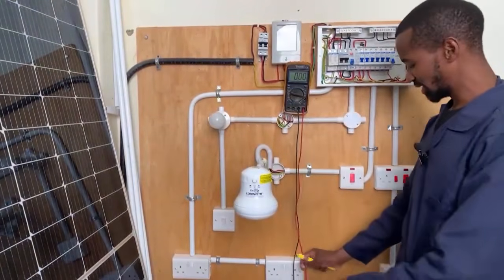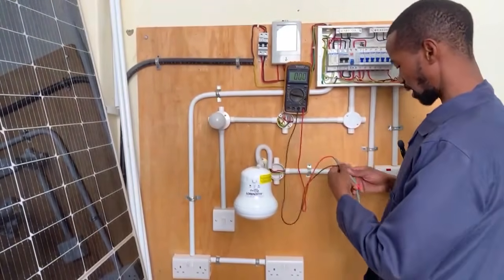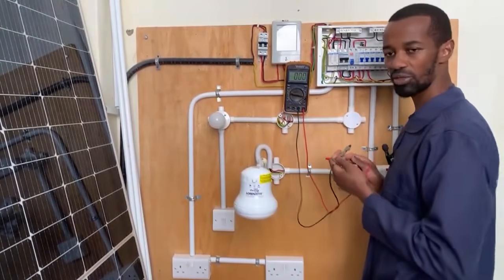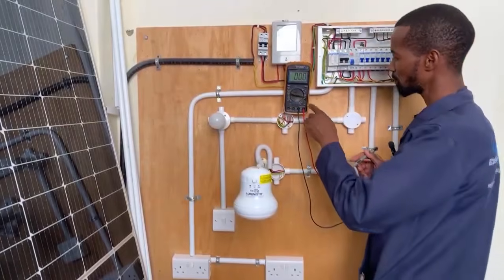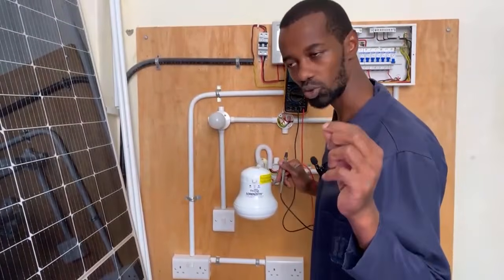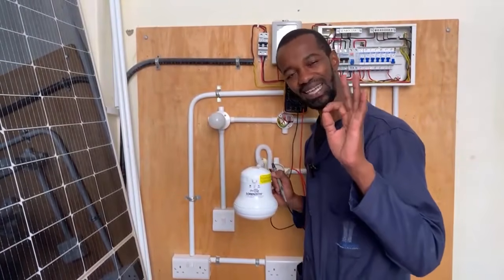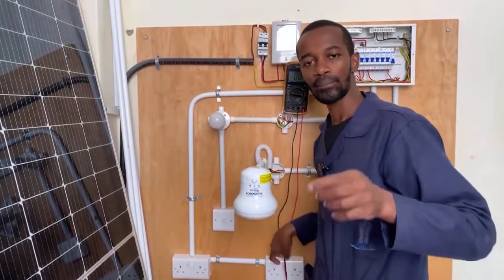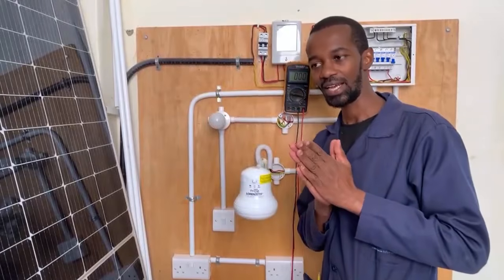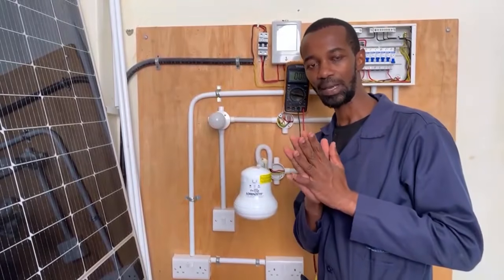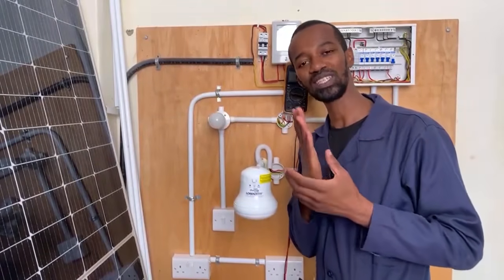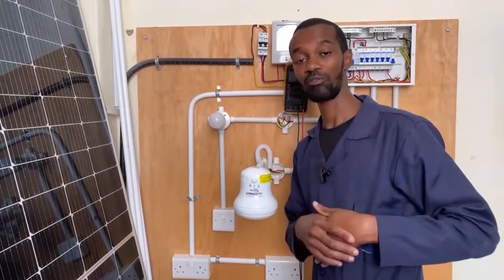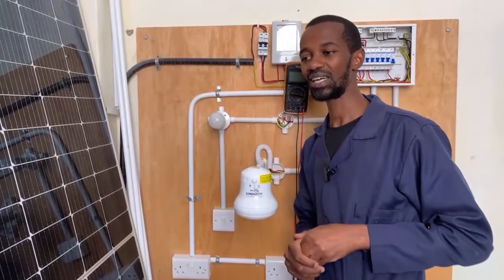Now, what I was saying is you have a digital multimeter set to AC. We expect a reading of more than 200 volts AC, so we will not place it at 200 volts, even though you were expecting exactly 200 volts. For instance, when taking a reading for a 12 volt battery, and your digital multimeter has the position for 12 volts, you don't place it at 12 volts. There are some batteries which are charged up to 14.5 volts. Therefore, you will not get the correct readings.